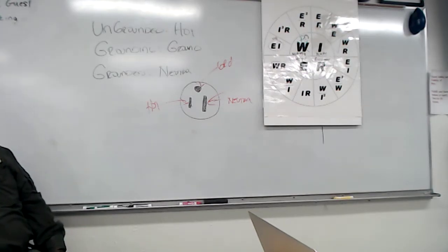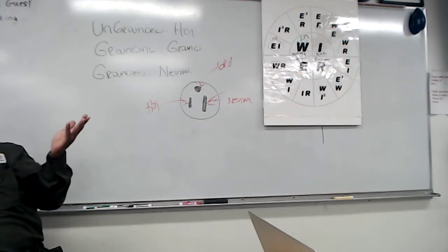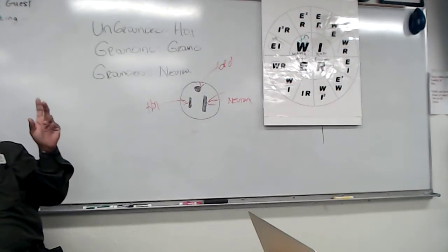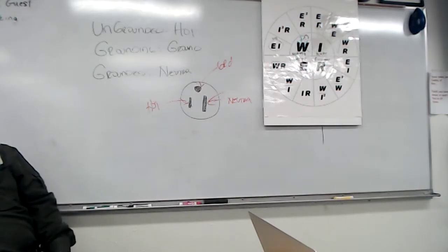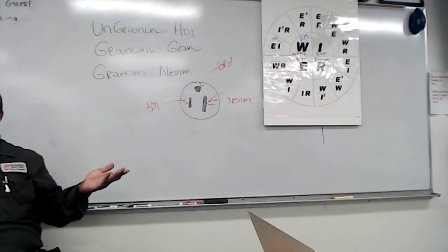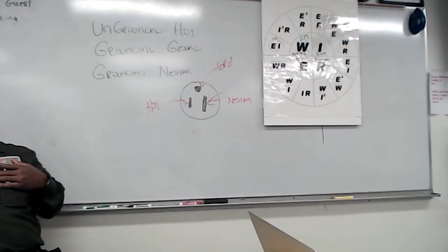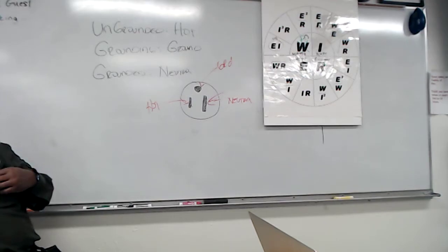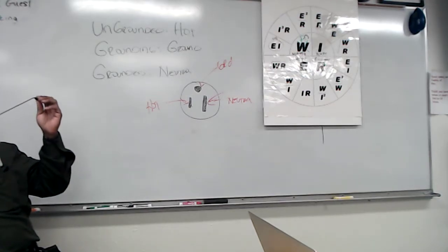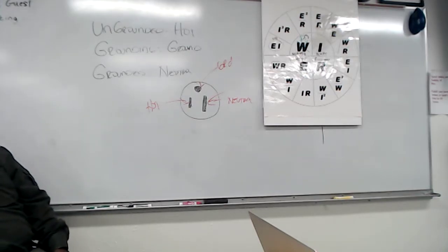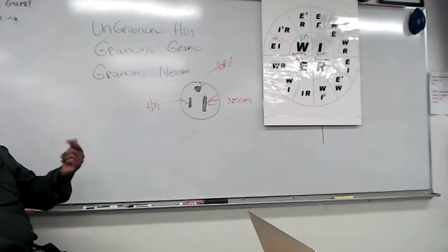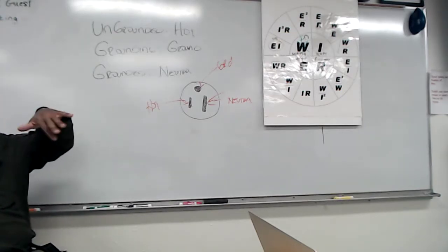Plus, it's required in commercial. Well, I shouldn't say required. Some commercial jobs require the ground up on their job. We're on a commercial job right now, and every single one of ours is ground down. It depends on the client. I think it's only government and daycare centers. It's based on specs, it's not code. They may say, on our job, all grounds up. Or the City of Fort Worth may say all daycares are non-city, grounds up.